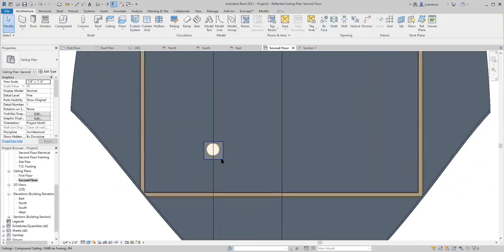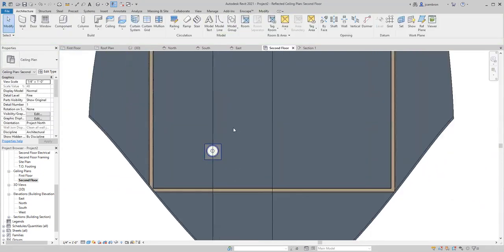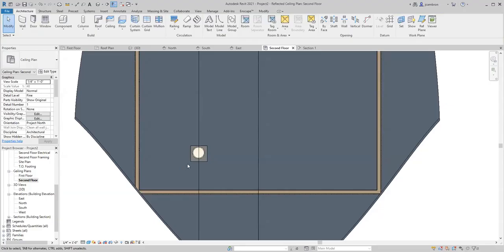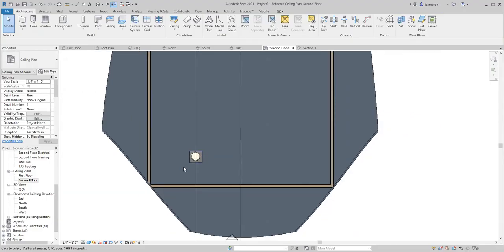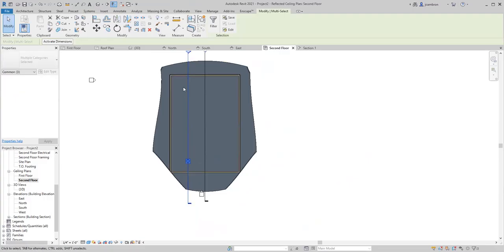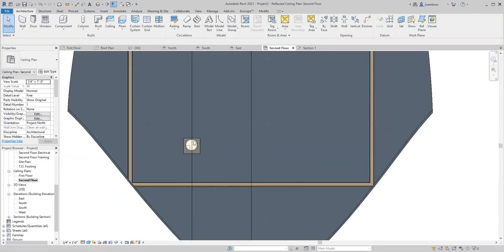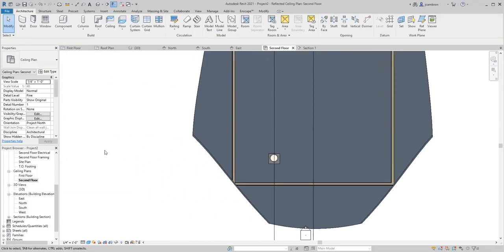There we go. Okay. And now I can go ahead and highlight, do a cross window around this. Notice that the cross window that I did was from left to right. So I click, drag, and move the cursor over it, which is different than going from this side over here, because then this is also going to select the section marker.